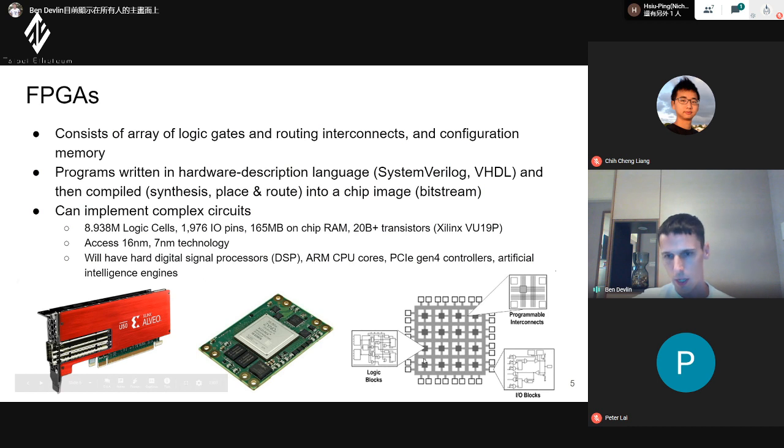And this picture here is showing what a basic view of an FPGA looks like. So you have in the middle these logic blocks I talked about, which will have your function. On the output, you have all of these wires, which are programmable. And then you have these IO blocks on the outside where you connect your inputs and outputs. You can see here on the outside.